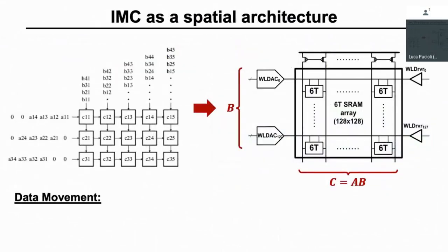In fact, I described in that analysis this in-memory computing, comparing it to standard memory accessing. But what about these architectures that try to optimize that memory accessing, things like these spatial arrays? Well, in fact, if you think about it, this in-memory computing architecture is really just another spatial array, where instead of these processing engines, which can potentially distribute memory and compute, I have bit cells in a similar arrangement, which can distribute memory and compute. And in fact, it's very interesting to compare these. Let me start by just comparing the data flow. Okay, then I'll go to the compute.